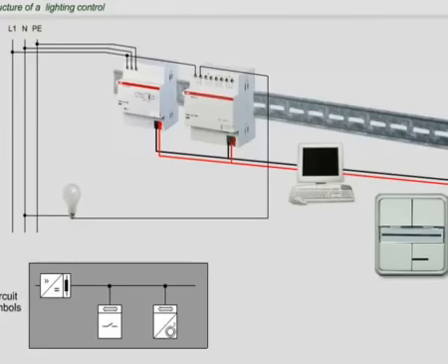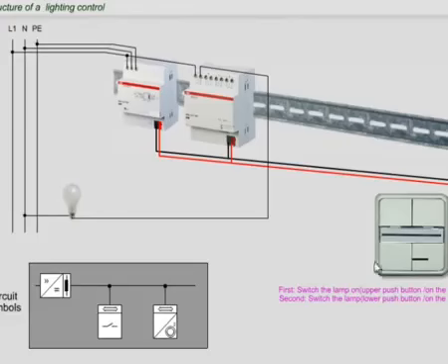All bus devices are programmed by means of a PC, so now you can test the system's functions. The keys of the push buttons have a neutral central position from which they can be easily activated. Now the sensor transmits electrical signals across the bus. These signals are also called telegrams. The actuator reacts to this command and accordingly switches the light on or off.